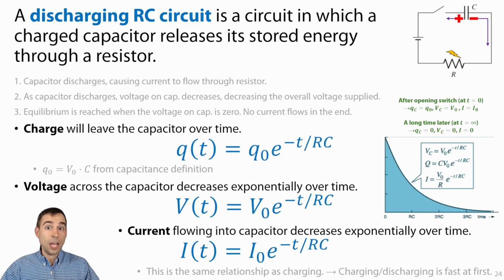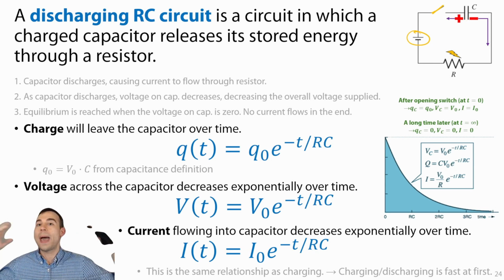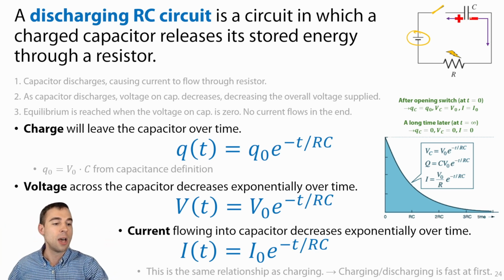So now that our capacitor is charged up, what happens if we open this switch? If I instead open the switch and prevent the flow of electricity from the battery itself, essentially all of the charges collected on that capacitor plate will recombine. They'll go back to their original starting locations. All of the negatives that collected on this plate will try to recombine with the deficiency of negative charges that left the negative terminal of the battery.